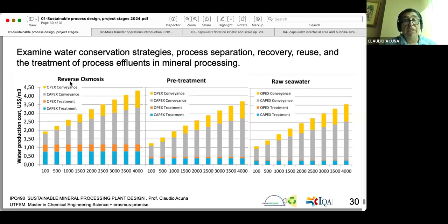to have pure water. It's important to understand, you can produce 5,000 microsiemens per centimeter. Potable water will have 200, 300 microsiemens, even sometimes 20 microsiemens per centimeter to drink. But this intermediate water will have 5,000 microsiemens. You cannot drink it, but it's good for flotation. You need to have some ions in order to generate small and stable bubbles.